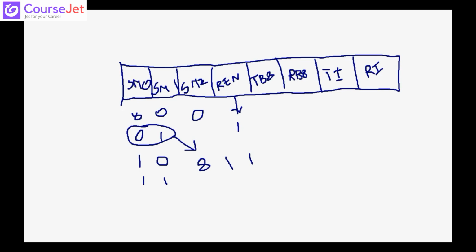In other modes, you will have 8 bits of data, 1 start bit, 2 stop bits, or 9 bits of data, 1 start bit, 1 stop bit, or 9 bits of data, 1 start bit, 2 stop bits.